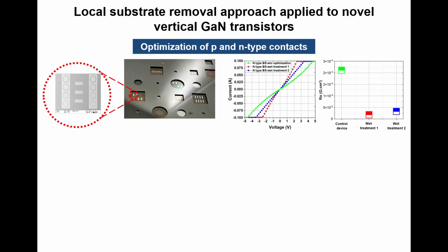I won't go into detail here. We thought it was easy. It was not that easy. But with these TLMs, with this approach, we could nicely optimize. You can see the results here. So you have basically no impact of this contact resistance on the overall on resistance, okay?